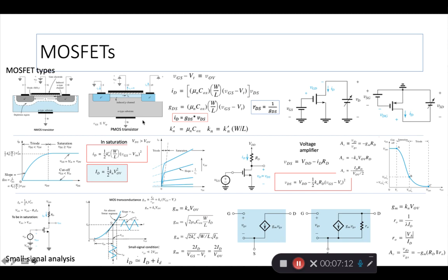Obviously, we are very interested in current, right? And current is generally shown as ID, the value of current that flows all the way through the circuit. Now we show, for biasing and for understanding the physics of the device, we show the circuit like this, but a more real circuit actually looks like this to the right, right? You have the bias voltage, the gate to source applied at the gate, and the other voltage is picked off of the drain, and the source here with the arrow, that is grounded.